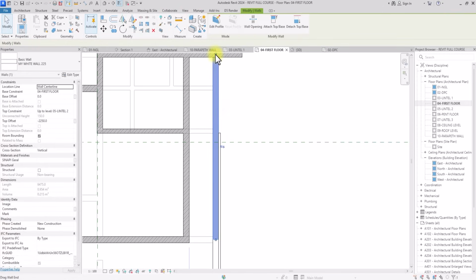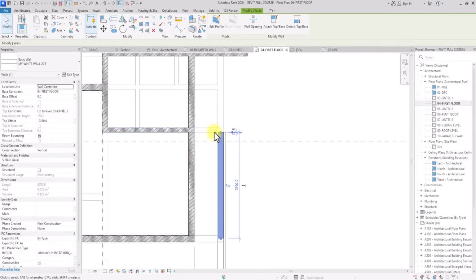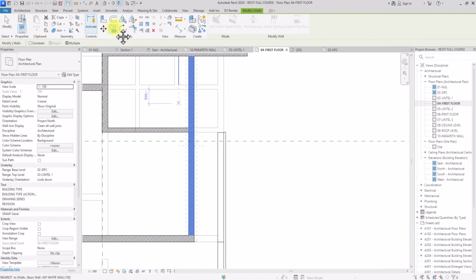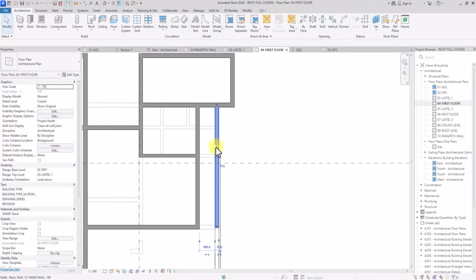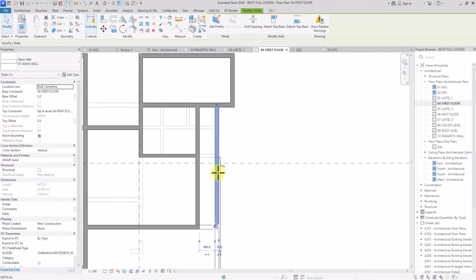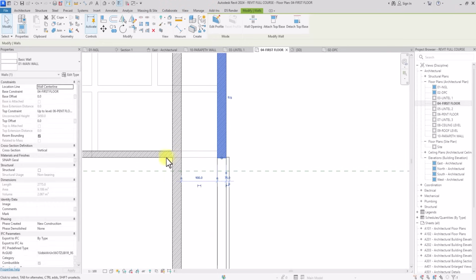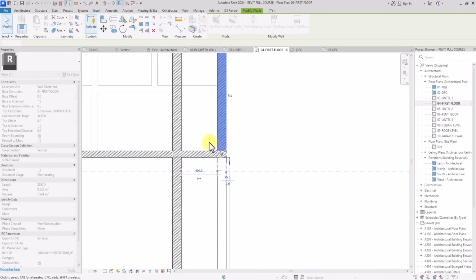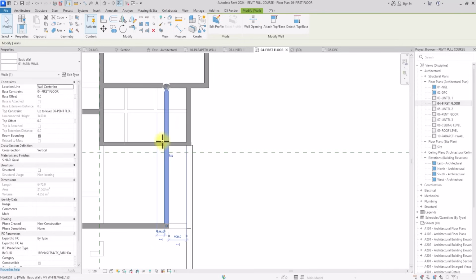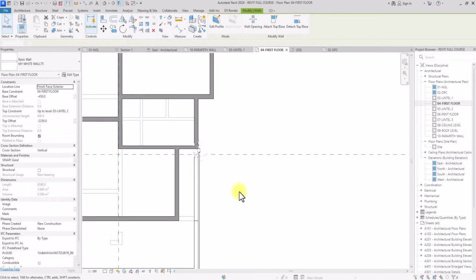So now I'm going to drag this wall back. The reason I'm dragging this back is because this is a convenience, so I don't want the convenience to be part of this balcony. So I'm just going to copy this and place this here. Of course it will clash because these two walls are overlapping, so I'm just going to drag this one back to this point where it's supposed to be. Then I'm going to drag this wall to this point and drag this here. So now it's at this position.